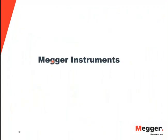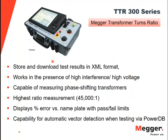Let's talk about some of the Megger instruments. We have a 3-phase turns ratio tester. It is capable of performing the test on all the 3 phases, 1 phase at a time with automatic switching. It has the capability of comparing the results with the nameplate and providing the pass-fail criteria. The unit is capable of working in a highly noisy environment in an EHV station.